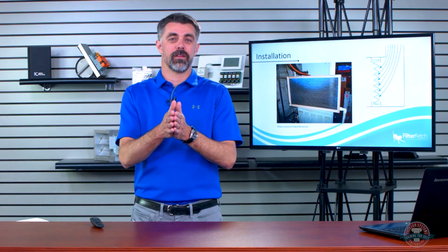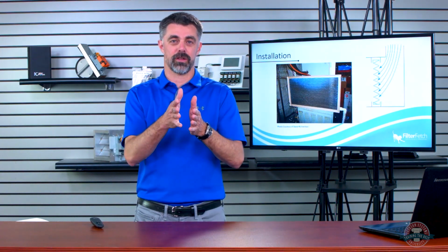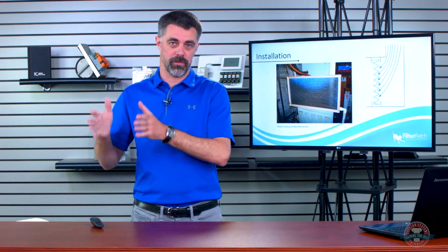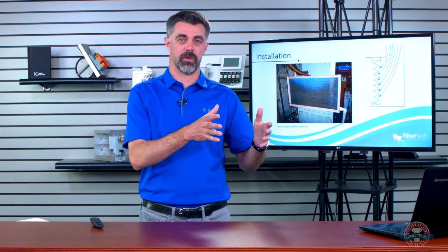Ferris wants to know, he said he's seen a few systems where the customer has more than one air filter, one after the other. One like a 2-inch air filter thick to get the 4-inch thickness. Is there an advantage or disadvantage of this kind of setup? Is there any gain in the Merv rating? Well, yeah, you're going to gain Merv rating because you're stacking filters. So it's not super additive, but the second filter is probably going to catch some extra stuff because the first filter already caught some, so the second filter is going to get to catch a percentage higher of that. So if you add the percentages up, you're going to catch more stuff going through.